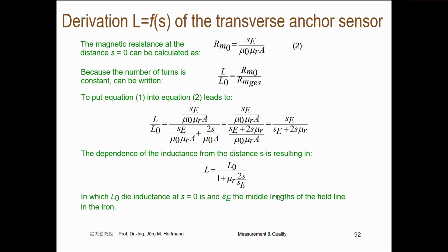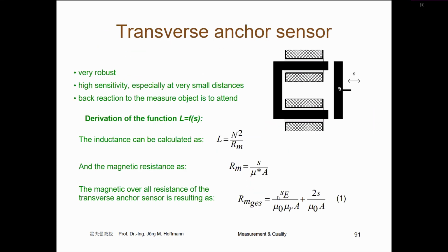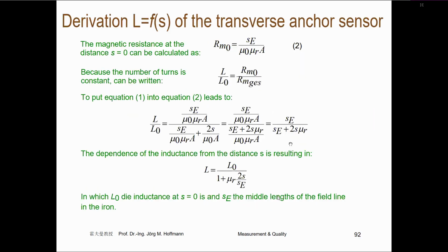So that expression would be 0 in the end when you go in an infinite way far from the sensor, and then you have this expression as 0, and here is then written the inductivity is L0, the basic inductivity, divided by 1, so L is L0.